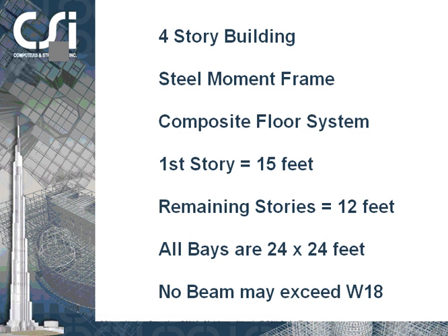Our project will be a 4-story building where the first story is 15 feet and the remaining stories are each 12 feet high. The bays are all 24 feet by 24 feet, and the lateral system will be steel moment frames. No beam may exceed a depth of a W18.